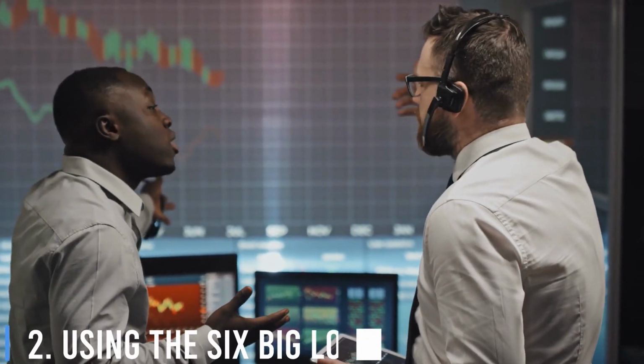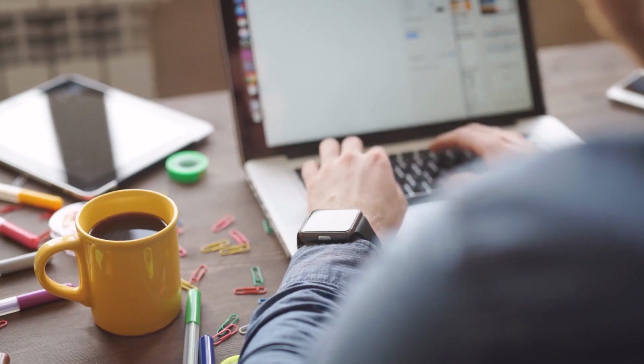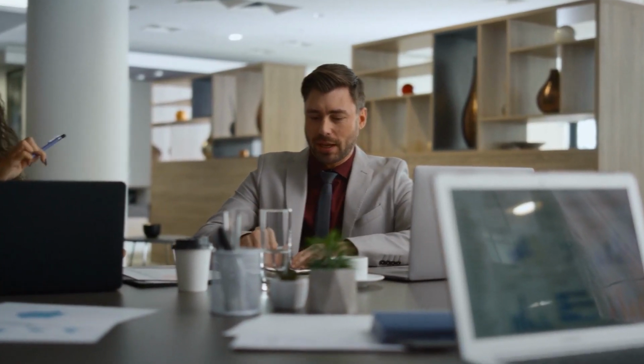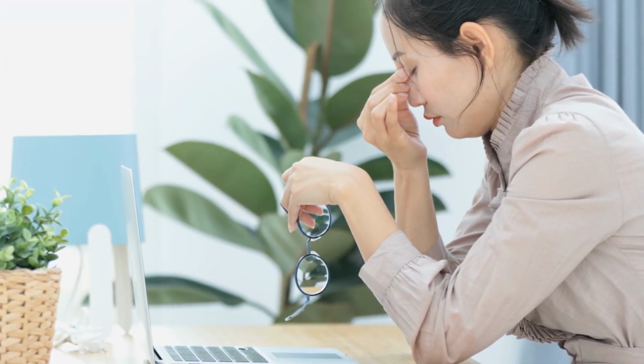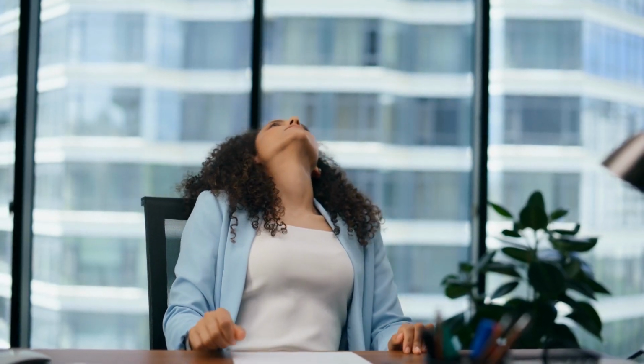Number 2. Using the 6 big losses. Using the 6 big losses framework creates a concrete path to improve your OEE score. Working to reduce availability loss in the form of equipment failures or setups and adjustments protects you against preventable unplanned stops or downtime, as well as minimizing any planned stops.